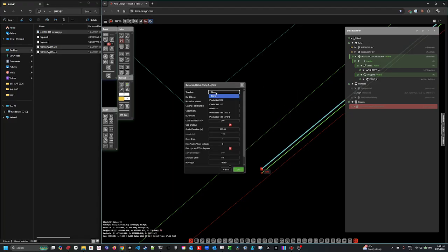And see here, we've already set up our templates. You can change it. We're going to use buffer. Just have to check these elevations because we don't want it on the wrong elevation. Just set it to 280 and this one to 270. You can use grade. This is ticked. Best to use the grade. If you're just doing length, then you untick that and you change the length. Right. We're not going to have sub drill. That's good. No angle. That's 115. That's fine. That's all good.